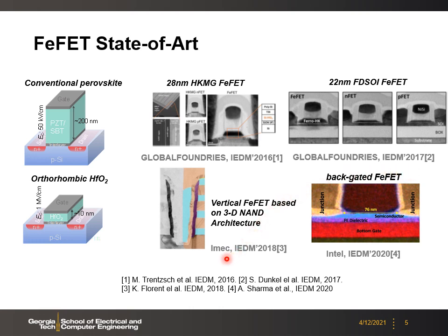And also IMEC demonstrated a 4-layer vertical FeFET based 3D NAND structure. So here the FeFETs are integrated as the sidewall of the trench. And at last year's IEDM, Intel reported a back-gate FeFET, which shows much improved endurance up to 10 to the power 12 cycles.